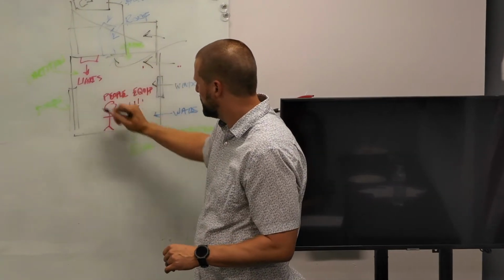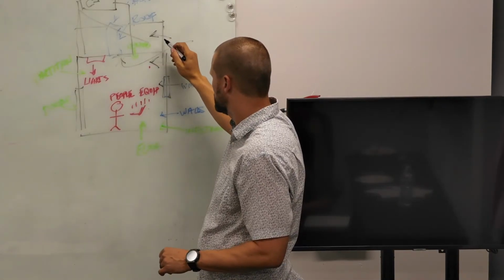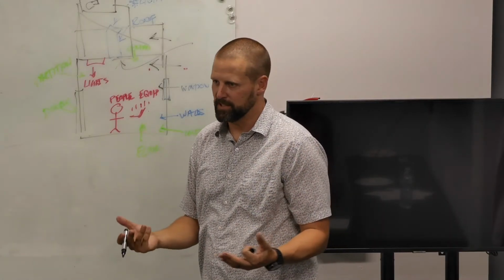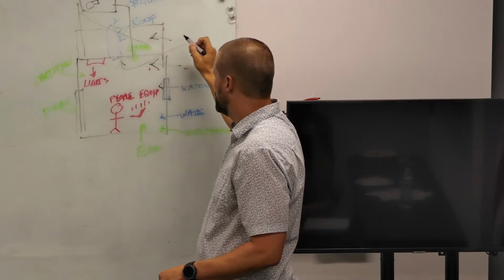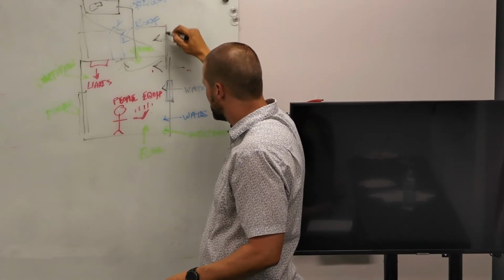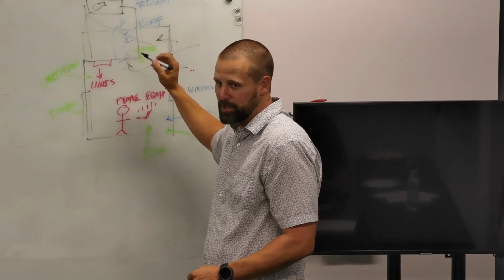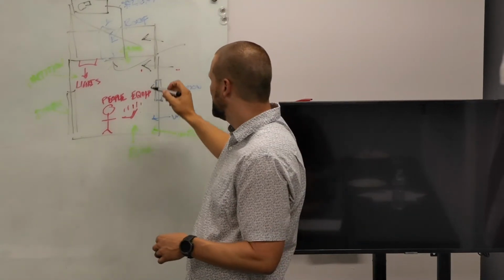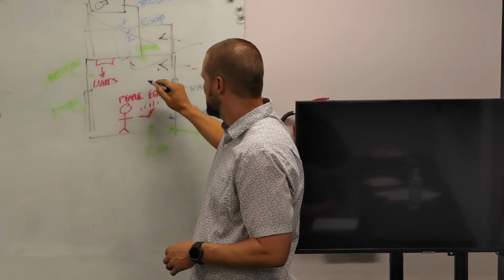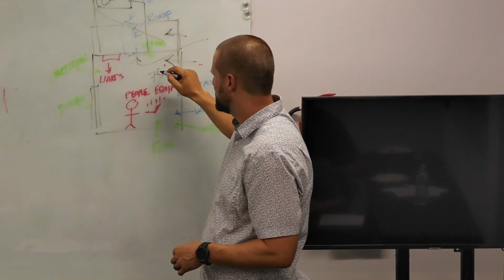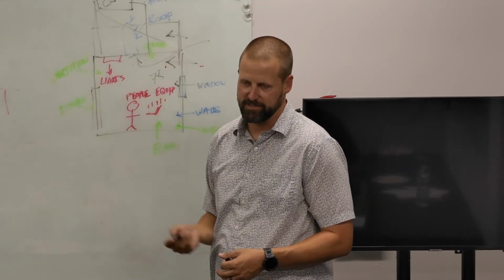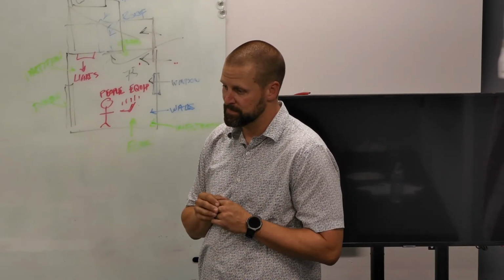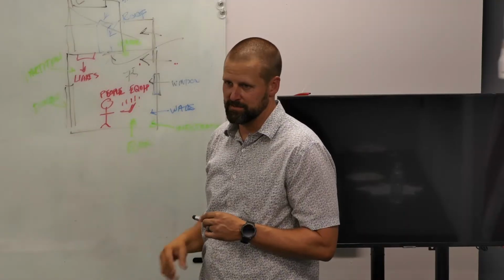But the airflow will be driven by the space, the return air temperature. If this is a VAV supply ceiling return, this return air temperature will get conditioned by this wall, and it won't require more air in this space. When I say conditioned, I mean it'll pick up heat from that wall. It won't require more air in the space, but instead of being 75, which is what the space return air temperature might be, it might be 76, 77. So there's ways to account for that depending how it exists and how it's in the load.